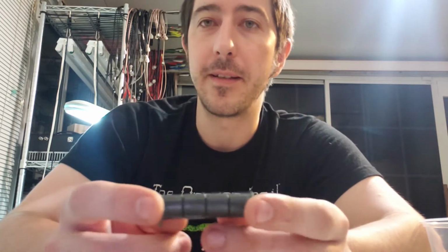The primary job of this inside of an RF amplifier is to transform the impedance from one impedance to another. So the primary job here is to transform the impedance of the transistor up to 50 ohms. That is pretty standardized throughout all of radio frequency operation.